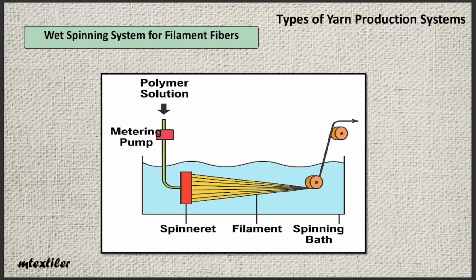After exiting the spinneret, the polymer, in the form of a filament, enters the coagulation bath, where the polymer precipitates and solid filaments are formed. The formed filaments are drawn by rollers to stabilize the polymer chains. Any solvent that remains on the fiber upon leaving the coagulation bath is washed off, and a controlled heating stage is also performed to stabilize the properties. The filaments are wound onto bobbins and are ready for subsequent operations, which may include texturing, cutting, twisting, or direct